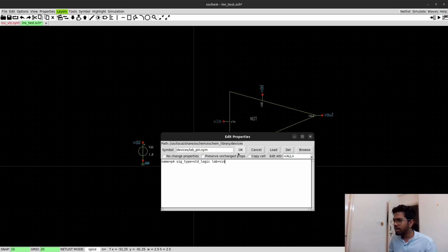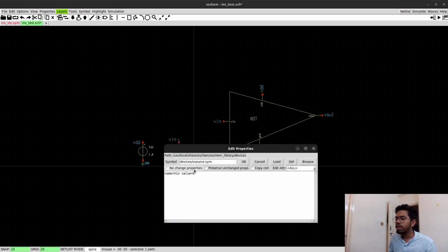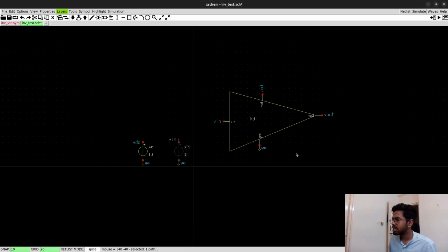We have given it 0 here. And we are not worrying about anything, because even if we give 0, in at least it will be 0, but we can overwrite it using our code block, right? So that's why for now we have given it 0. See what we're gonna do today. We're gonna do VTC, voltage transfer characteristics. For VTC we do DC simulation only. So today we'll do DC simulation. Transient simulation we will do specially for knowing rise time, delay time, and also power consumption. And we'll do those things in a later video.